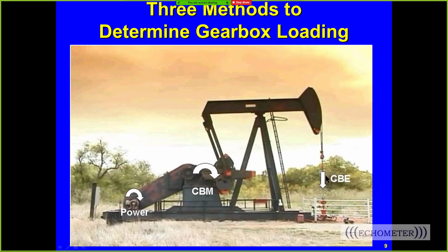Now, this is just a picture kind of trying to show that there are 3 methods. And the CBE method has an arrow here saying that you were able to hold this crank level and balance the rod loading, with the weight of rods and fluid plus the pump load. That's some of the pump load slips off. You balance that load with the effect of the weights, and when you release the brake, this crank stays level for a short time. And you note that time and you identify that load, and then you know you've measured the CB load, the load that balances with the effect of the weights, and that's on the upstroke. So you're doing this test on the upstroke.